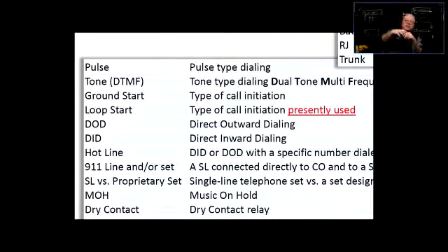So yes, the CO circuitry would recognize the number by the pulses, but when the automatic operator picks up and you have the voice announcement saying press 1 for this, press 2 for that, it is looking for those tones. And if it doesn't get those tones, if you have the line programmed as pulse, it's just going to get those pulses and it's not going to understand that.